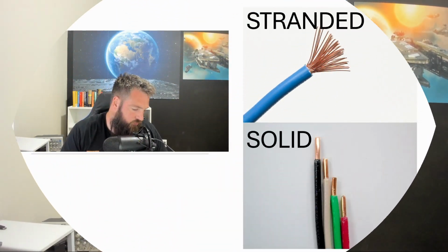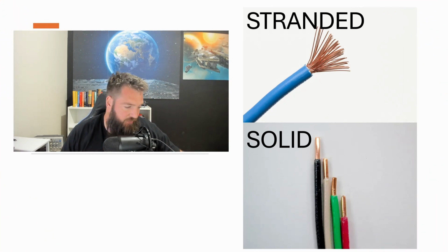This is like a ferrule, and it gives you the capability to take all these stranded wires and feed them into here, and you crimp it off. Now this will be typical for stranded cables. You'll need something to be able to terminate this on the other end. You don't necessarily need that for this wire. They make all different types of devices for those. You've got ferrules.